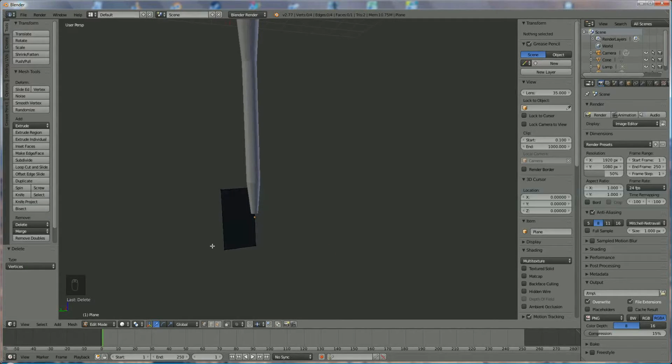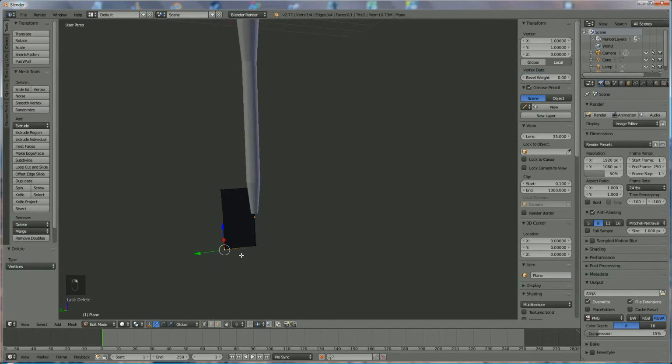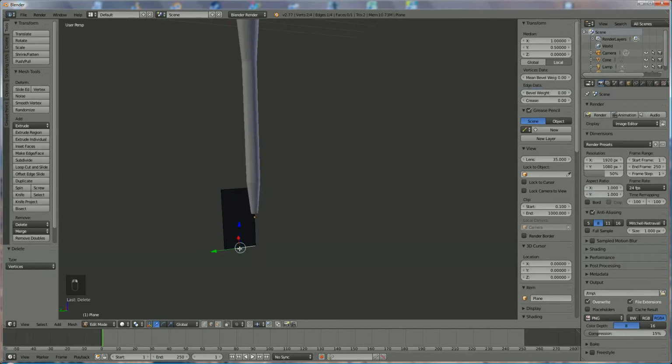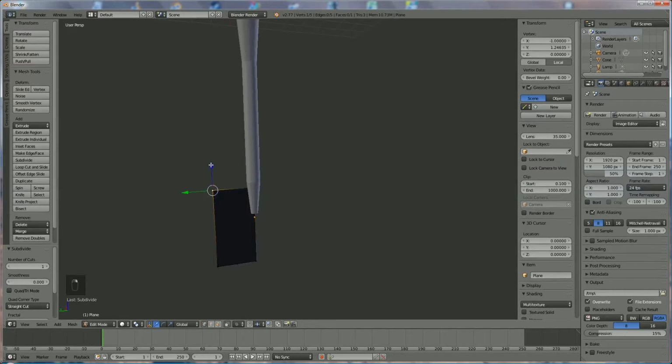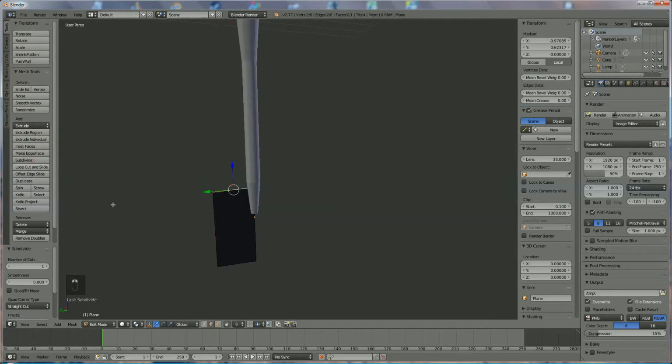Now we're going to change the shape a little bit. To do that we go to edge selection, of course. We enlarge it a little bit. We're going to bring that also a little to the outside, and we're going to select that, subdivide it in two, go to point selection, where we're going to select that point, and bring that point down a little bit. But before we do that, we have a certain straight line over here, so we're going to subdivide that one also in two, like this.